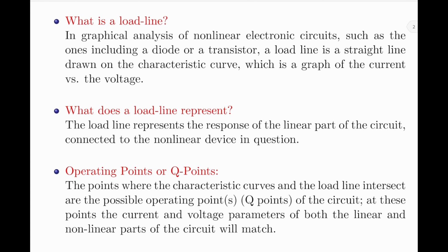The next question that we should ask is, what does a load line represent? Well, the load line represents the response of the linear part of the circuit connected to the non-linear device in the circuit. Please note, when I say linear part of the circuit, I am referring to the circuit elements such as a voltage source and a resistor. And when I say non-linear device, it is either the diode or the transistor that is being used in the circuit. So, in simple words, we can say that a load line represents the constraint put on the voltage and current in the non-linear device by the external circuit.